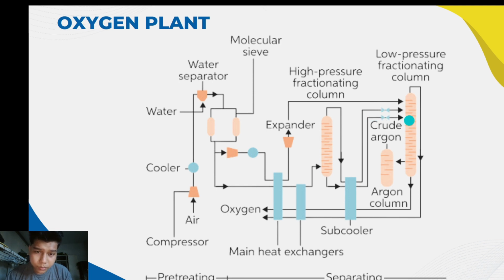As the argon vapor reaches a point about two-thirds of the way down the column, the argon concentration reaches its maximum of about 7 to 12% and is drawn off into a third fractioning column, where it is further recirculated and refined. The final product is a stream of crude argon containing 93 to 96% argon, 2 to 5% oxygen, and the balance nitrogen with traces of other gases.